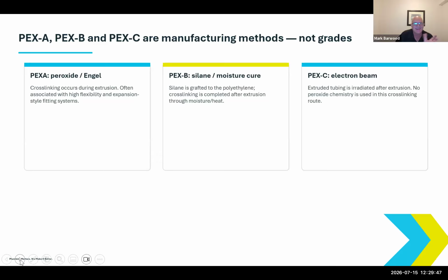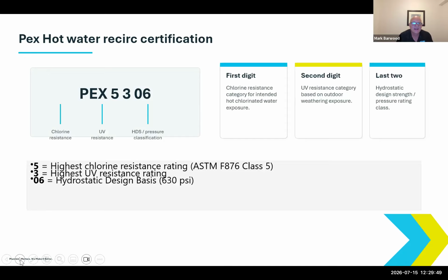Really neat. Glad that synergy worked out. I think one of the questions that was asked was about hot water. We're starting to see in certain condos now in Toronto, I'm hearing stories about, you know, we had this with copper on recirc lines. Copper was failing, pinhole leaks all over the place. A lot of that was attributed to not the greatest water quality and the velocity of the recirc pumps being too high, and now we're starting to see some cracks developing with PEX.